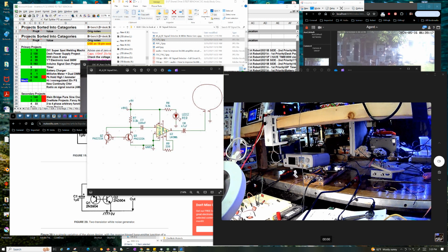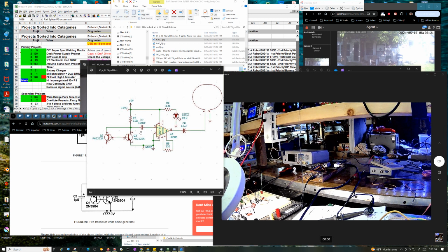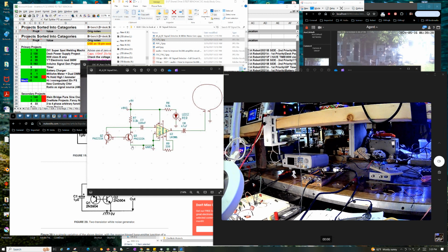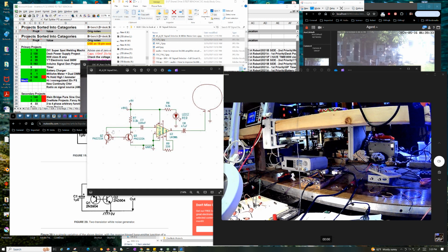So again, given how he designed this thing with no resistor here, I was thinking, well, maybe he's not wanting to overload his amplifier, because it's supposed to be a 9-volt powered circuit. So this might actually reduce the noise level, but then, I don't know, it just seems kind of off base that you should have a resistor here to limit the base current through this circuit.